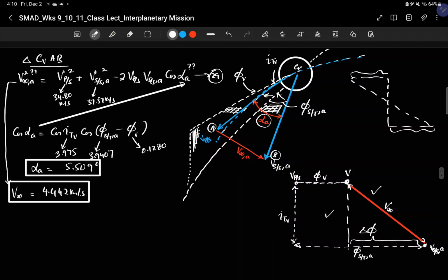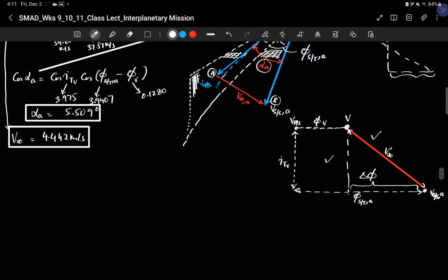This is the velocity that is still available to the spacecraft as it is approaching the planet. Then that planet will impart its own delta V, which is the gravity assist, and a new velocity will be created for the departure from that place. By the way, this is the velocity with respect to the Sun. This is the V infinity that the spacecraft is carrying with respect to the Sun and not with respect to the planet itself.